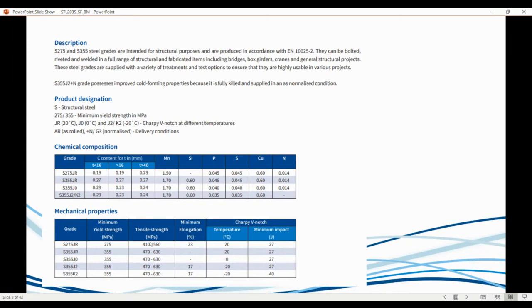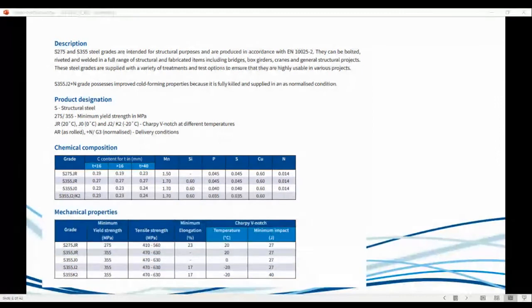The whole point of that is that, specifically for maritime applications, you should be aware of something called the ductile to brittle transition. As steel gets colder, it becomes more brittle. I don't know if you guys are aware of that transition. I think the Titanic failed because of that particular thing. You guys aware of that?